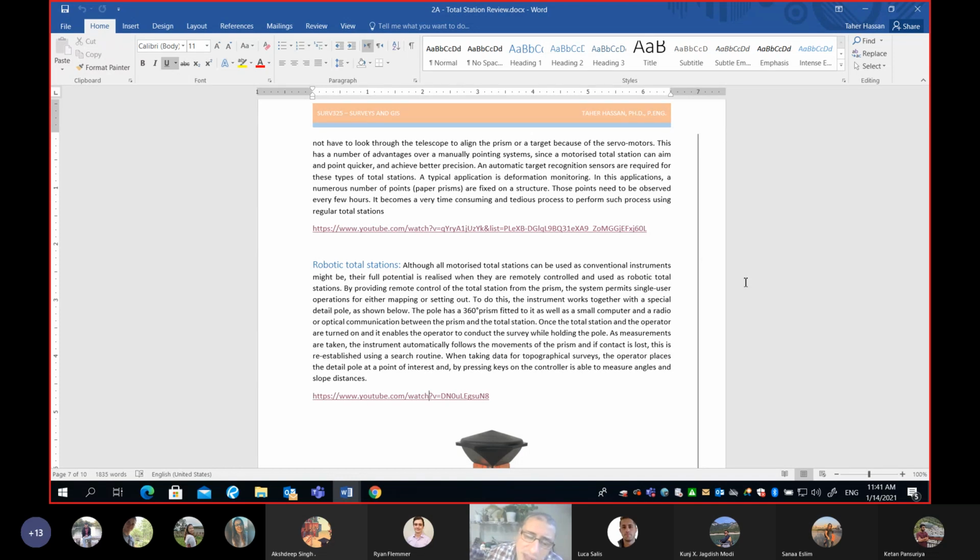Number two, do I need a backsight? I'm asking you something that we said a few minutes ago. Backsight. Do I need that for a robotic total station or no? No, it is very smart, it can know everything. What do you think? You need a backsight. Exactly. So remember, even though it's very advanced and very expensive, you still have to do a backsight.